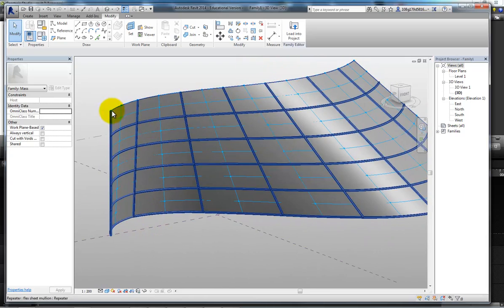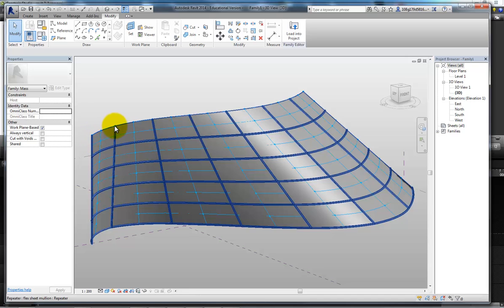It works quite well. To fill in these gaps in the mullions here, you have to make an adaptive component that's just the mullion, which involves drawing a line through 3 adaptive nodes and adding that profile along it to replicate what you've done previously in the panel you just built, which is quite easy.